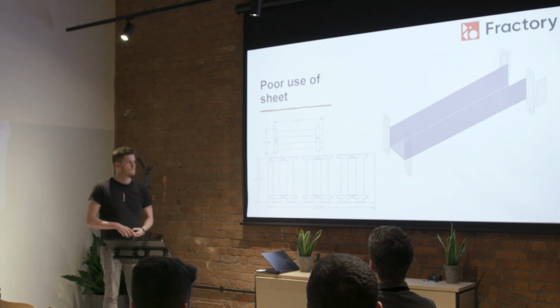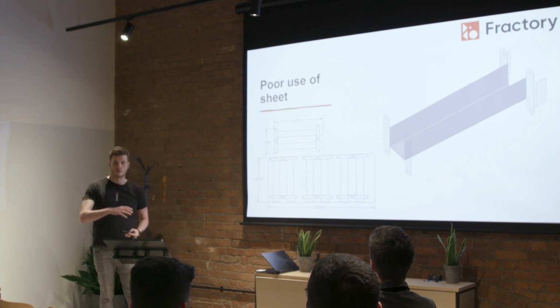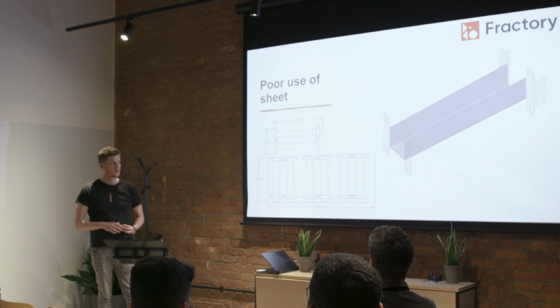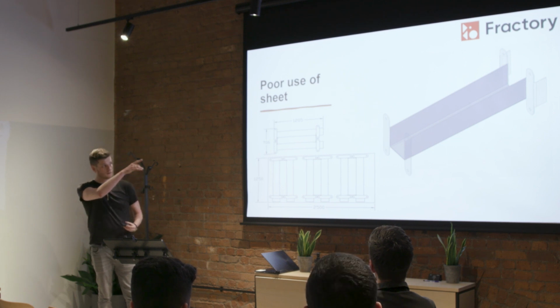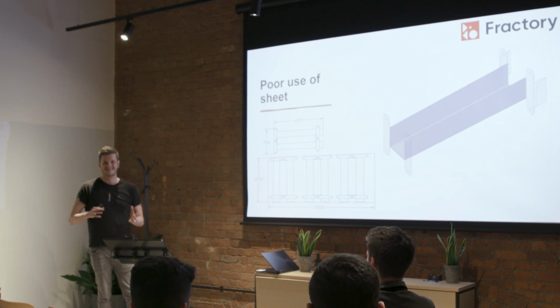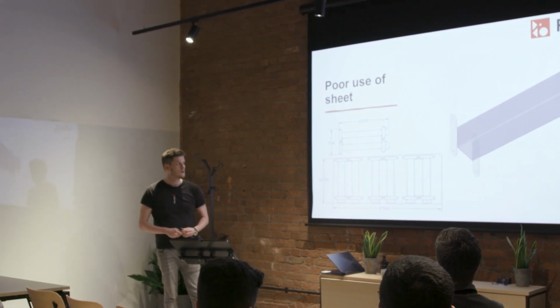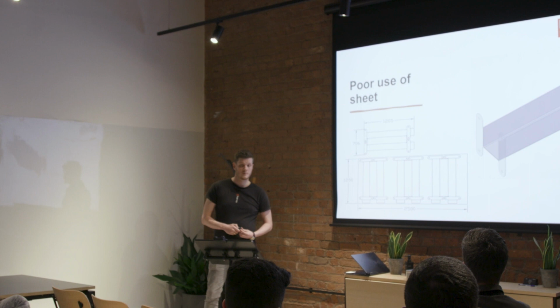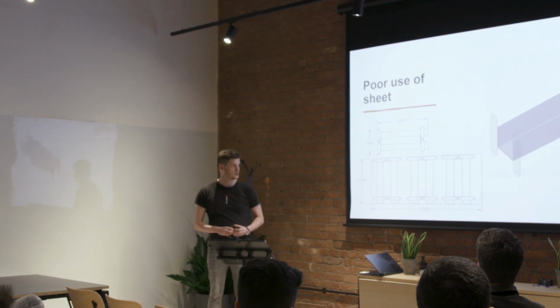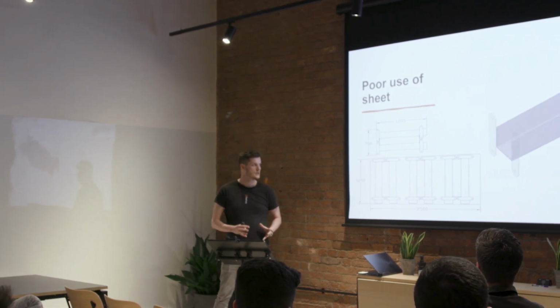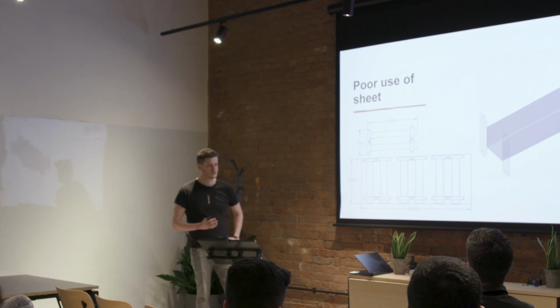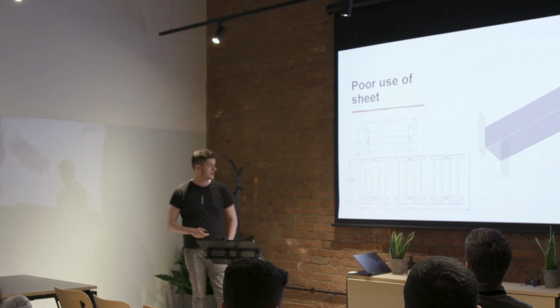Now, another factor is that if this was a smaller order, the actual cost of setting up the welding for putting these on might mean that you're not really saving too much. But again, on larger projects where you are making a higher volume of these, you will be saving a fair bit of money just by getting 4 onto the sheet rather than 3. But it's always something to consider when you are doing your designs.